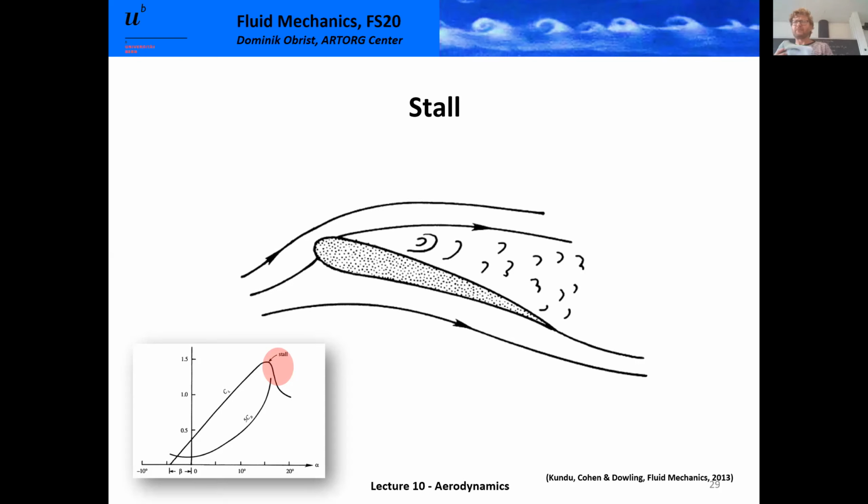So many people are confusing stall with turbulence. Stall is not a phenomenon of turbulence. Stall is a phenomenon of flow separation. And we know separated flow usually has turbulence associated with it, but that's not the problem in the first place. We even know that having a bit of turbulence in a boundary layer may delay the flow separation.